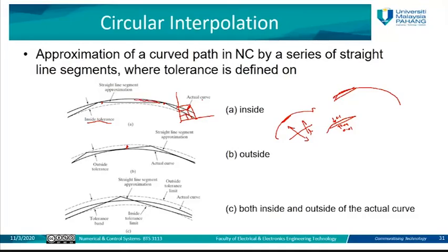I mean, you segment this line into multiple 2-point lines, but with small segments. In this case, you are going to increase the accuracy. So the path generated by the interpolator will be very close to the original one, so no more tolerance. Okay? Okay, sir.